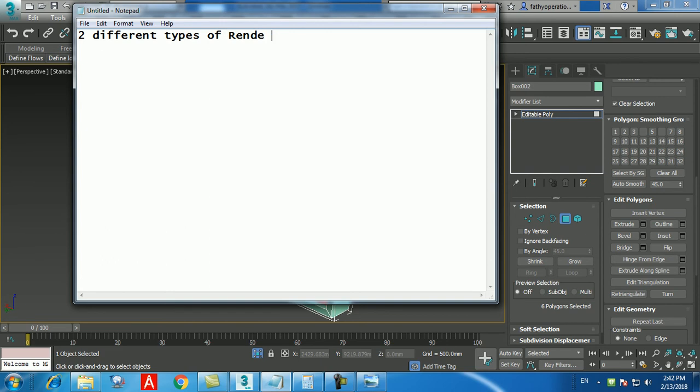First one, whenever you switch on 3D Max, if you choose classic, it will take the render called default scanline render, which is a very basic render which comes with 3D Max. And when you apply material, you will be applying standard material. So when you have the standard material, you will do every setting, how the glass should look, how the metal should look, how the water should look. So you are in control of everything, nothing is done for you.